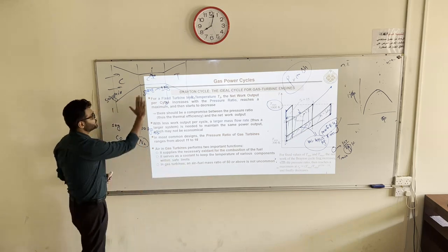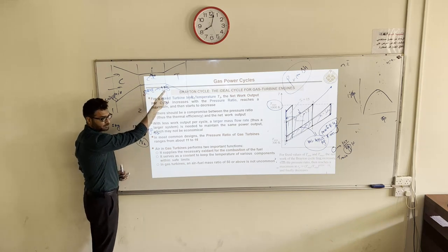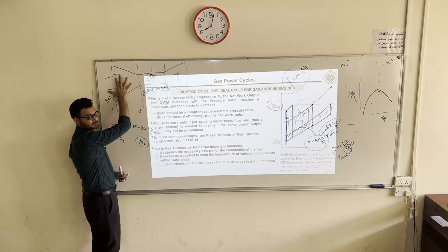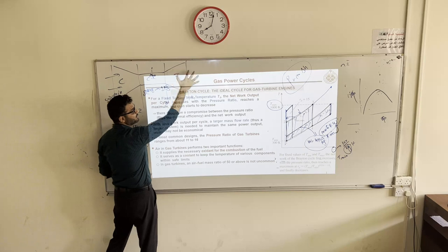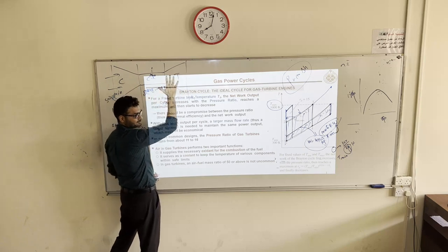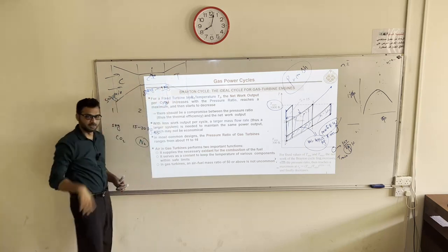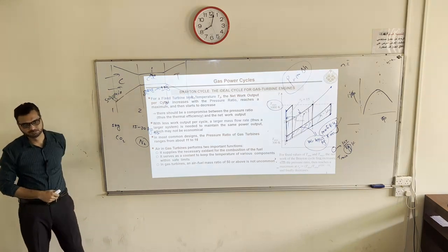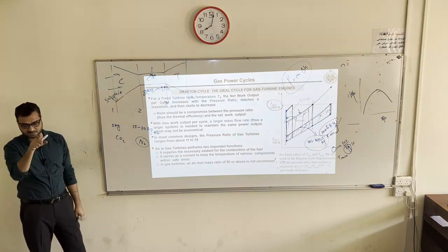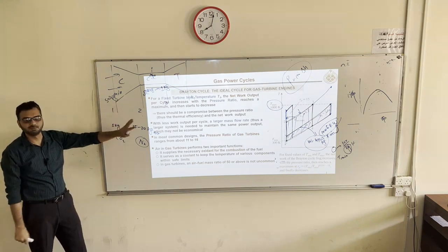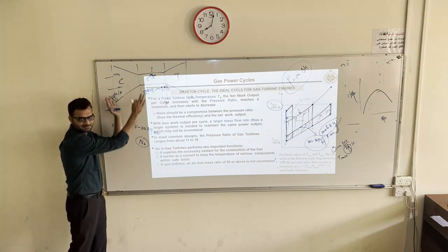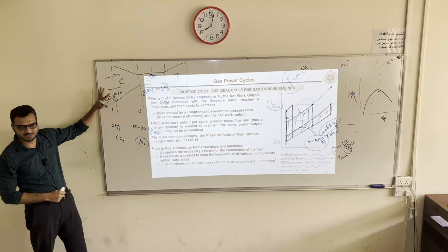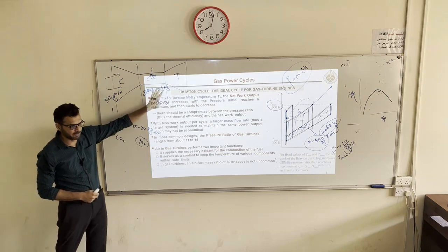Look, only 20 kilograms was required to burn 1 kilo, but we are supplying 50 kilograms. So the air standard assumption is more valid here than in Otto and diesel. If you do not like this assumption, it's more valid here, because you are supplying much larger air than required.